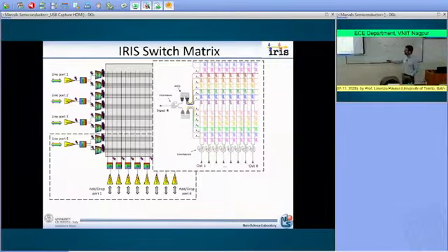On the single fiber, we have up to 12 different wavelengths traveling, and so we need a grating that is able to couple any of those 12 different wavelengths to the input line. And then here, there is the first function that we have implemented, a function that is called an interleaver.